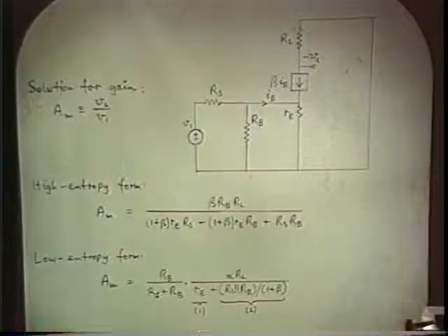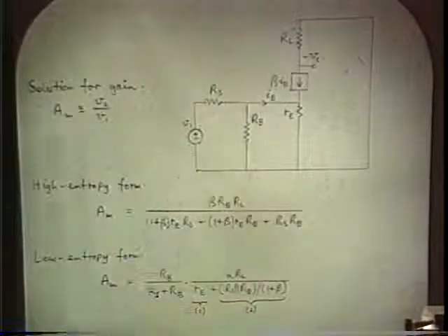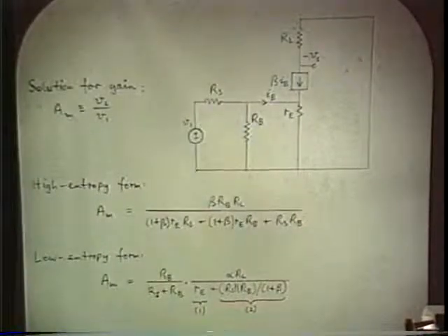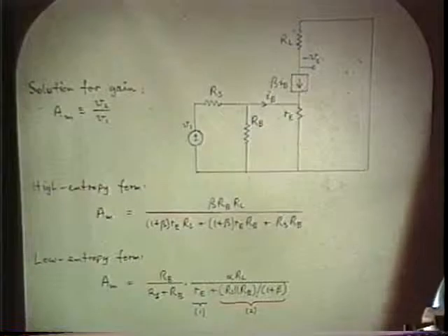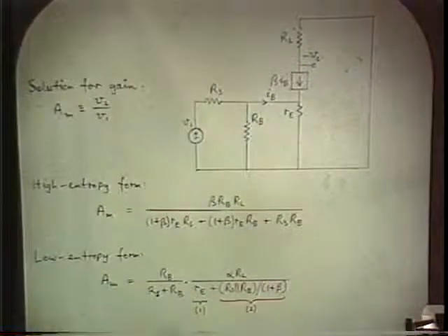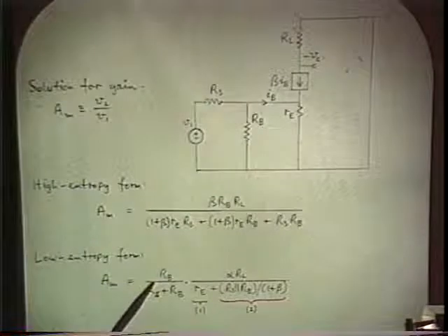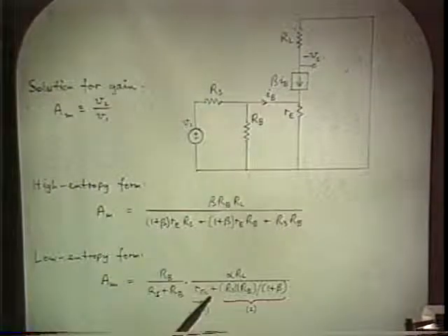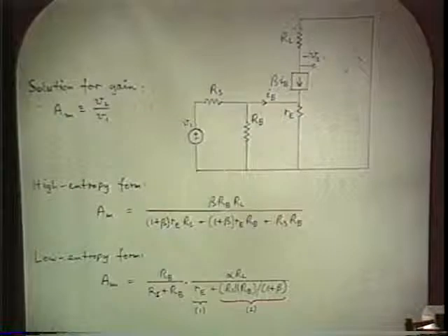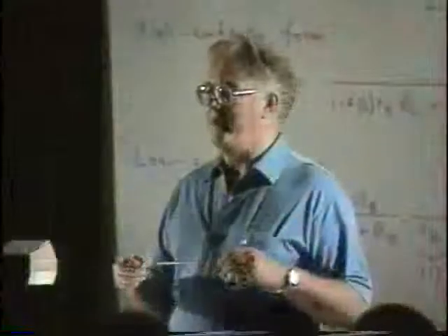The second one is all of the resistances in the model, which would generalize to impedances, show up in one of two forms, either as ratios, in this case a voltage divider ratio, or as series parallel combinations. And the value of that is, you know that a series combination is dominated by whichever value is larger.